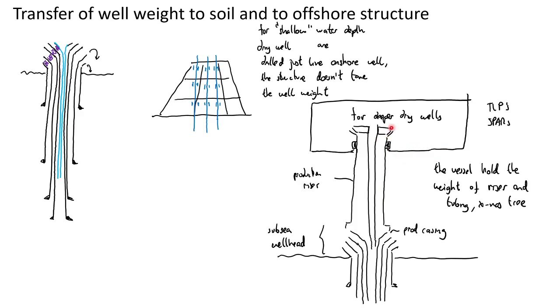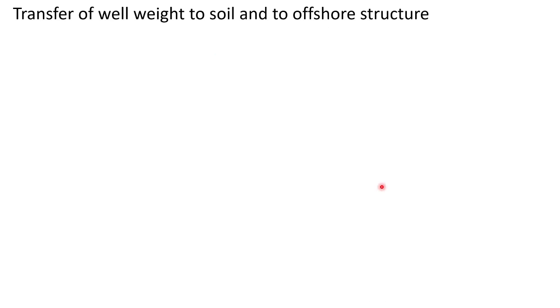This is an undesired situation because you can create a lot of stresses on the riser, and might cause fatigue and failure. Also, if you have too much drifting of the structure, or too much heave, movement in the vertical direction, then the seals between the tubing hanger and the well might be lost, and you might have some leakage. So this is something that is usually undesired.